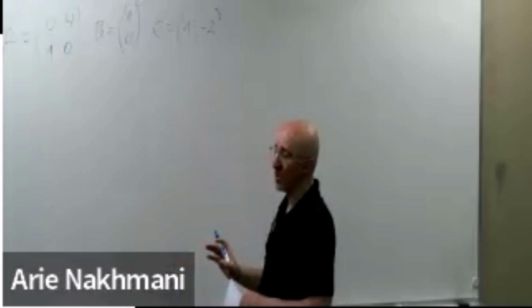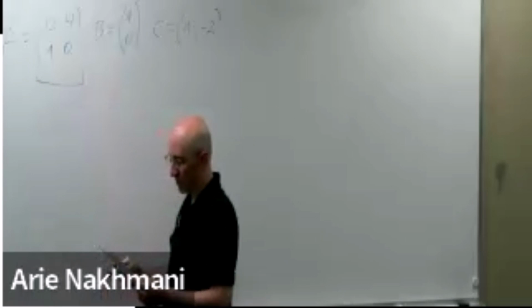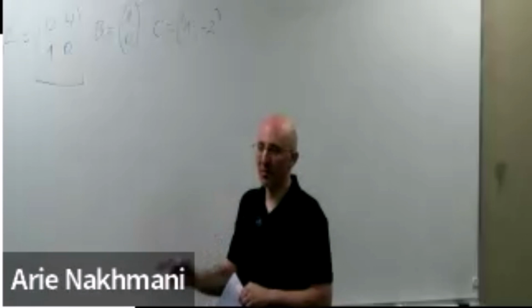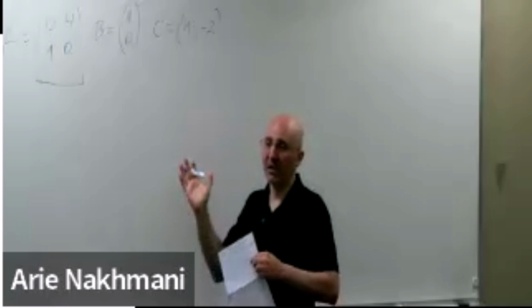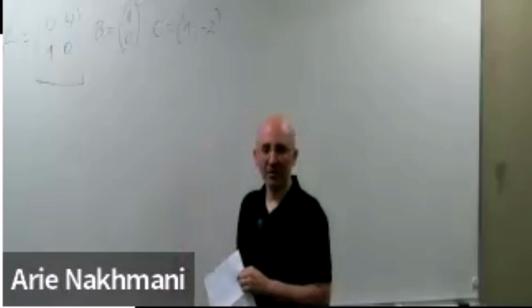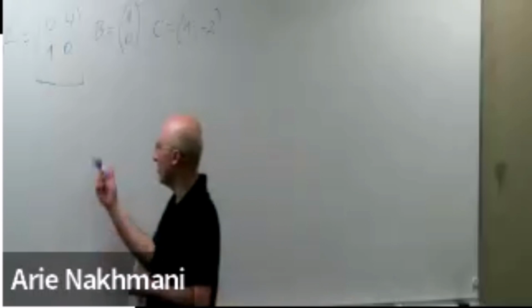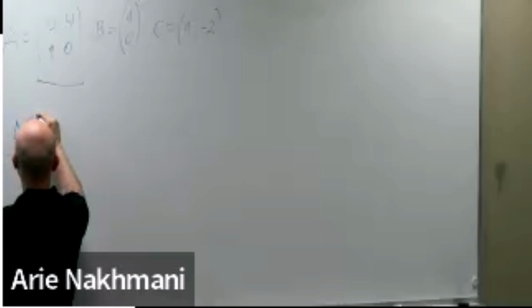To find asymptotic stability of that system, all I need to know is the eigenvalues of that matrix. If they are in the left semiplane, and I'm talking about a continuous time system, the system is stable, period. If not, it's not. Done. All right. So what is the characteristic polynomial of that matrix?